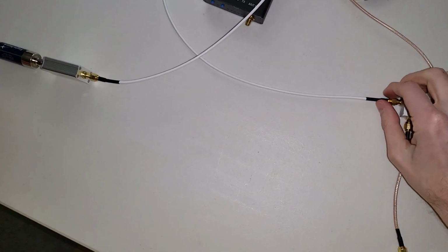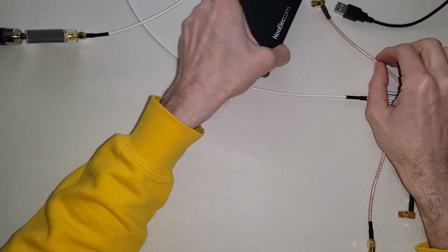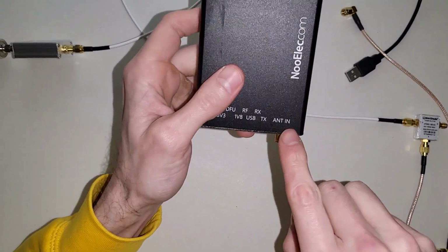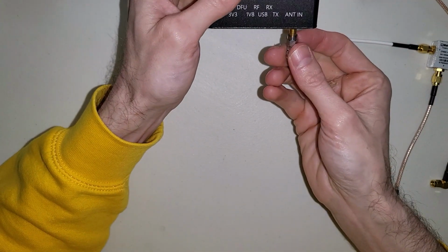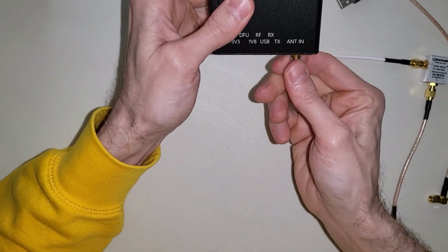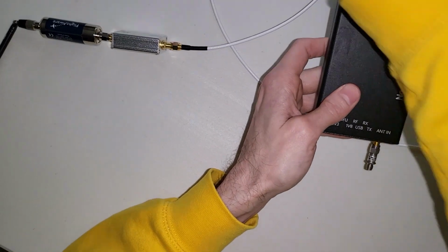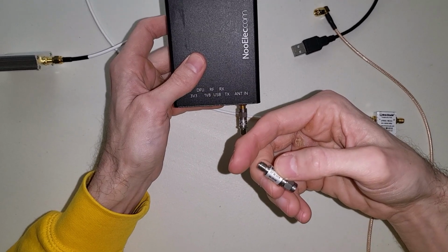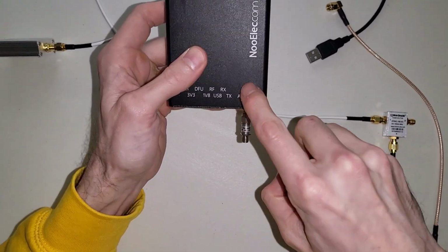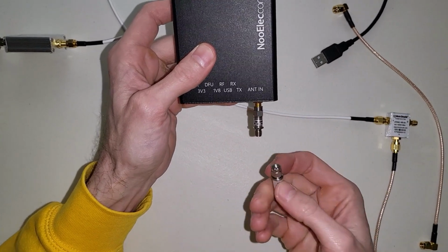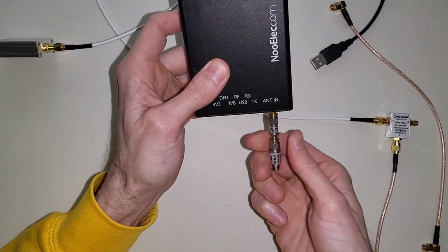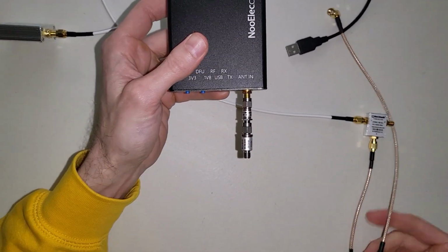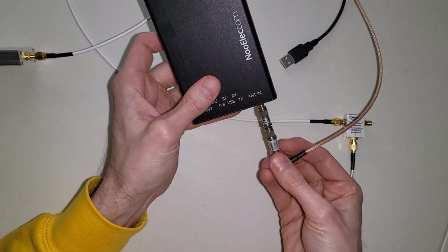Next, we'll connect the HackRF. So first connect the attenuator to the port labeled ANT on the HackRF. And we're also going to connect this device. This is called a DC block. All this does is ensure that the DC voltage output from the dongle doesn't reach this HackRF. So just daisy chain that onto the attenuator. Now, using an SMA cable, connect the HackRF to the power combiner.